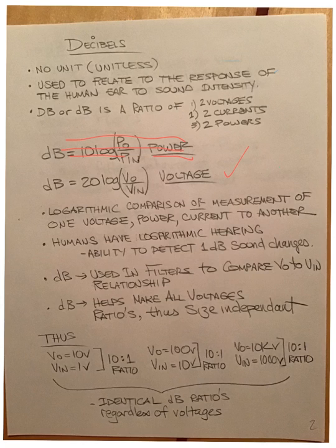This requires a little bit of explaining. This bracket that you see here is not, I repeat, is not a multiply function. You have to take V out, which might be 5 volts, and V in, which might be 3 volts, plug those values in here and evaluate the log of 5 over 3, and then multiply it by 20.